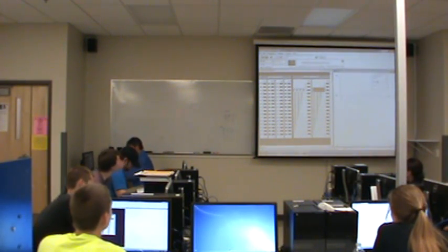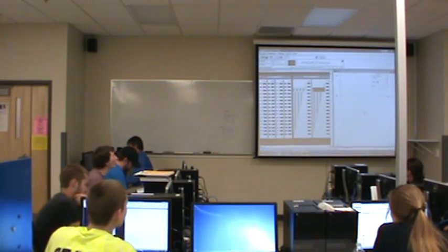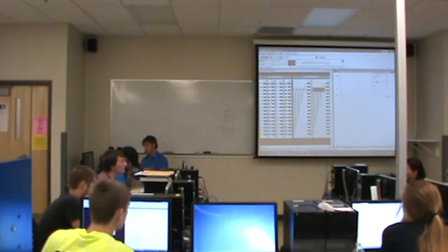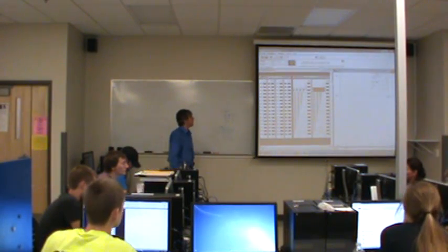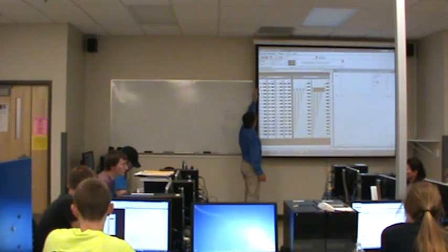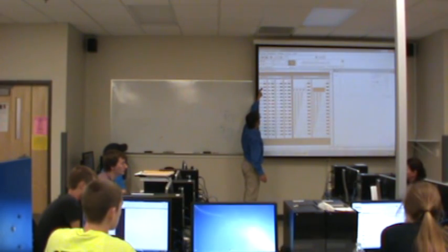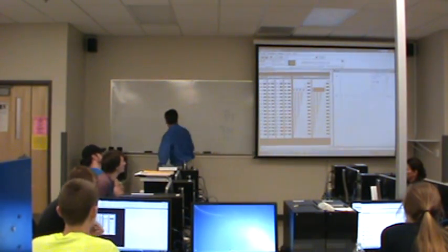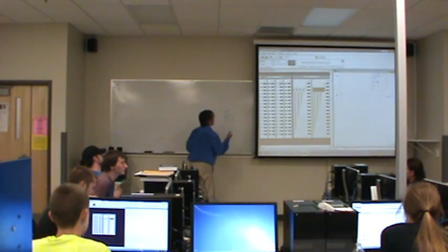So I'm basically going to take the status of all these switches. I'm going to mask it. I'm going to make it ignore some of the switches. Which switches do you want me to make it ignore? How about if we just ignore all of the odd numbers? The 1, the 3, the 5, the 7, and so on. Okay. So the mask that I would use would look like this.